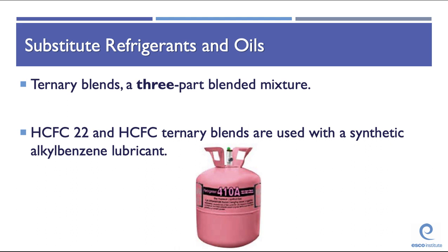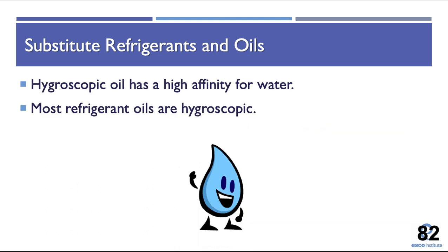There are several refrigerant blends commonly in use. Some of the blends are called ternary, which are considered a three-part blend. Ternary refrigerants are used with synthetic alkylbenzene lubricants. Make certain that you're using the correct oil for the refrigerant. Most of these blends have a temperature glide.